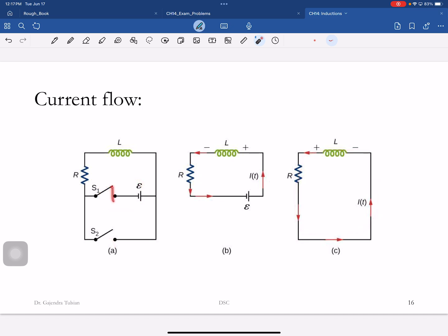Okay, so when this switch was closed, the current was flowing like this. This was a steady current. And then we're opening the switch, closing that. And what will happen is, see, this current is trying to decrease when you remove the battery, but this guy will try and maintain that current. And you'll maintain that current in the same direction. And now we want to see the behavior of this current. We want to get the functional form of this current. This current, again, will last milliseconds. Okay? Because, again, these devices cannot store a whole bunch of energy. You can't cook your pizza with them.